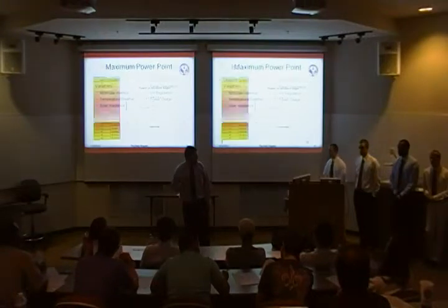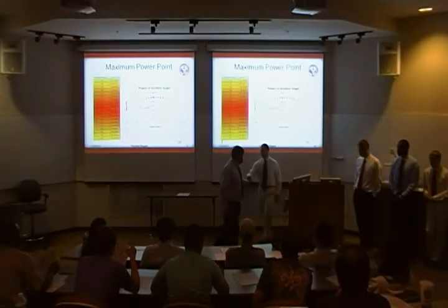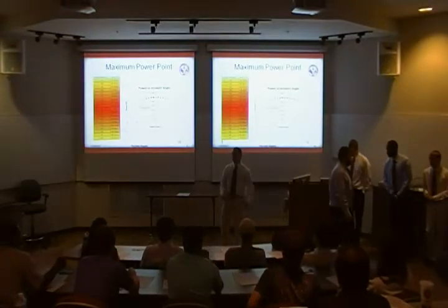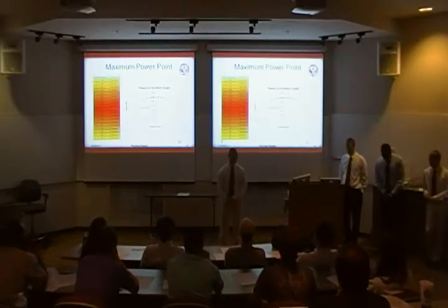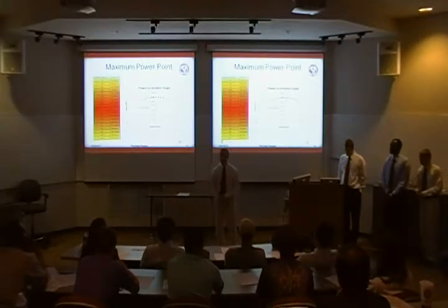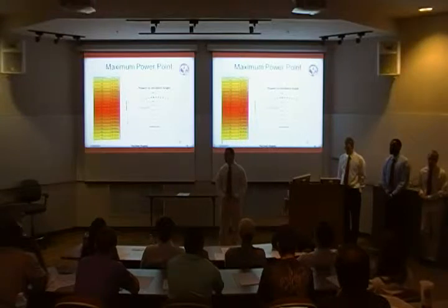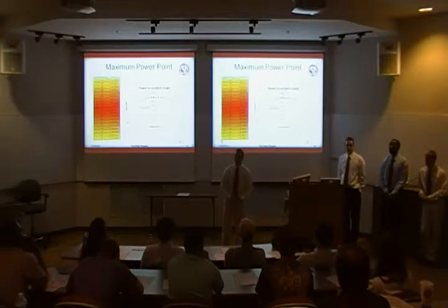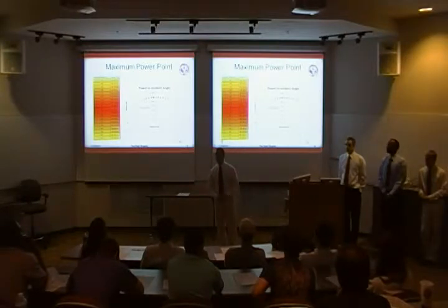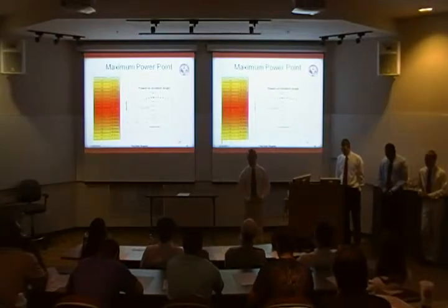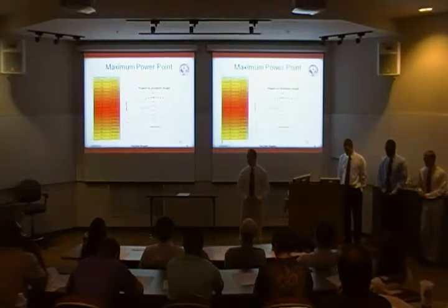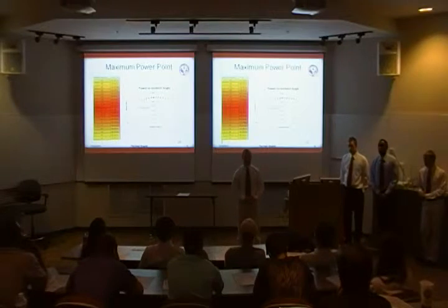Now to explain MPPT, Michael Mayhall. All right, our goal is to achieve maximum power conversion through panel orientation. To do this, we first have to understand how panel orientation affects power conversion. A lot of lab tests have been done to show that a panel will provide maximum power conversion when it is positioned perpendicular to the sun's solar rays. As this graph shows, you tend to lose power by a factor of cosine theta as you shift between plus and minus degrees of that position.